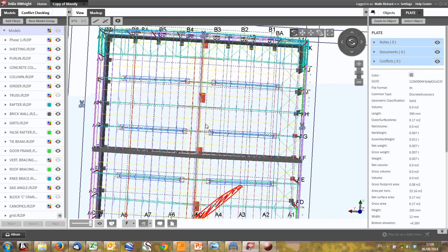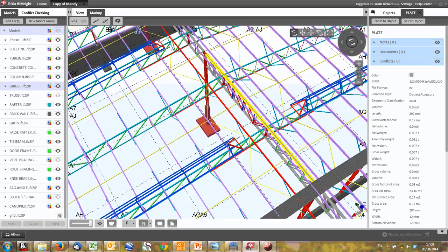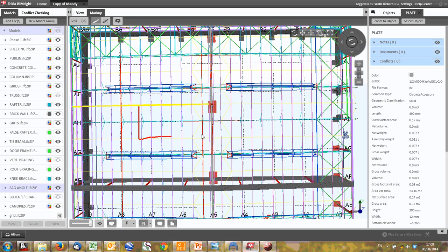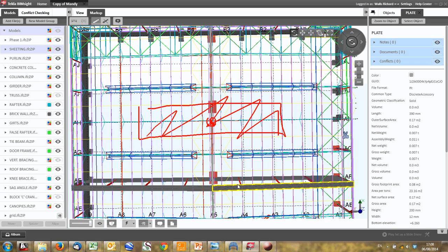So if we wanted to work out what is the load from this truss, what is the reaction down on this girder, once again, sort of half, and all of that would be acting on that one truss and providing a reaction force there in the middle. That way you can check your reactions, you can check your calculations, make sure there's nothing funny going on. Obviously, if this is stiffer in the middle, it would probably attract between 55 and 60% of the load. But it also depends on the stiffness of the outer columns and various other things. So it's half, but obviously the stiffer areas do attract more, so we might add on a little bit there.